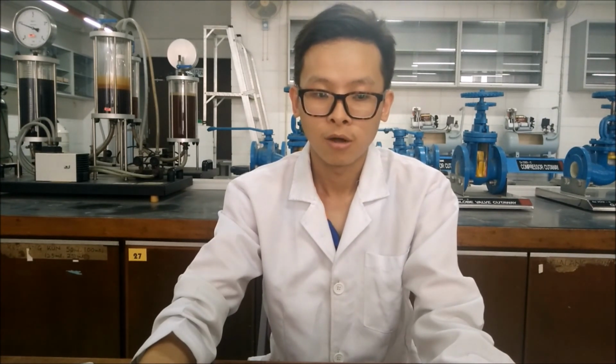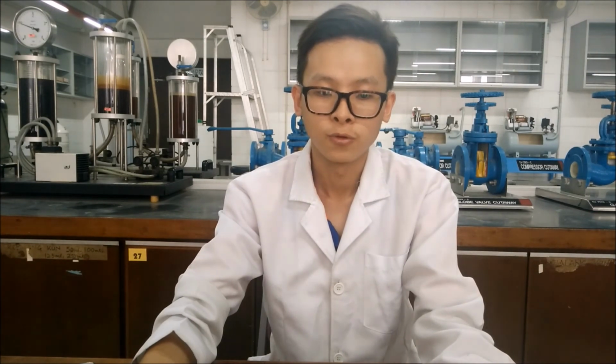The MMA synthesis reaction using the ACH route begins with the initial conversion of acetone to ACH by the reaction with hydrogen cyanide. The ACH is hydrolyzed in the presence of sulfuric acid to a sulfate ester of methacrylamide. The sulfate ester then undergoes methanolysis, or reaction with methanol, to yield MMA and ammonium bisulfate.